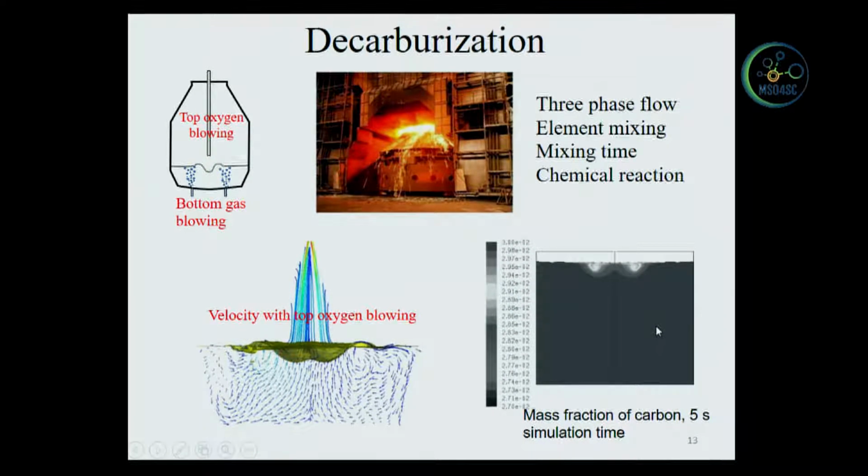And we couple the CFD model with thermodynamics. We simulate the decarburization process. This figure, the bottom figure, shows the carbon concentration in the metal bath after 5 seconds.